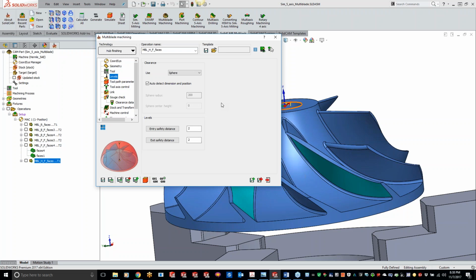So do they have any plans for 5-axis? Yes, they're actually more working on plans for more of the 3D iMachining finishing right now, but that is the plan. And with iMachining and the algorithm that's built in, it is quite the complex animal, just because it's all based off a chip load and an axial contact point of the tool, and when you start getting into ball end mills, that completely changes the scheme of things. So they are in the process of getting that. My assumption is once they get that set for 3D, it should carry over into the 5-axis side of things for you.